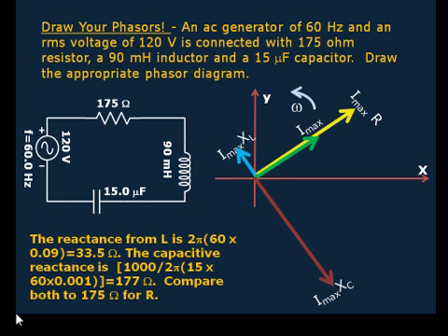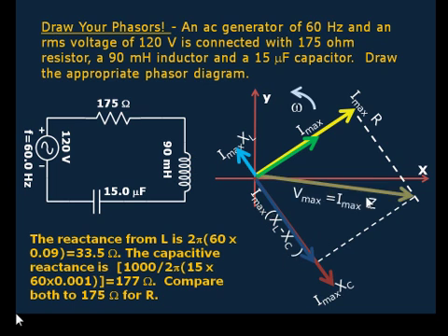So now the total reactive part of the voltage would of course be given by the difference between the inductive and the capacitive parts, and that's shown here by the bluish arrow. And given the total reactive value of the voltage, we add that vectorially to the resistive component of the voltage. Let's go ahead and do that. And the vector addition of these two voltage values, I max R plus I max times XL minus XC, turns out to be in that direction.